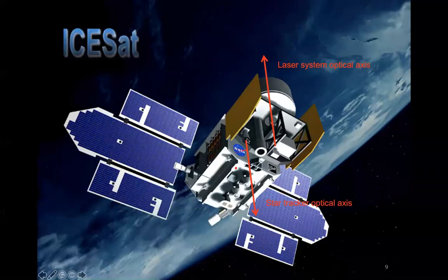So this is our star sensor. The star sensor is fixed to the body of the spacecraft, but in general the axes of this instrument are referred to the boresight of the instrument and the optical plane, so the focal plane of the instrument.